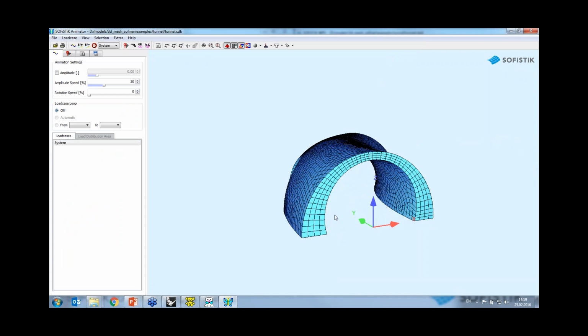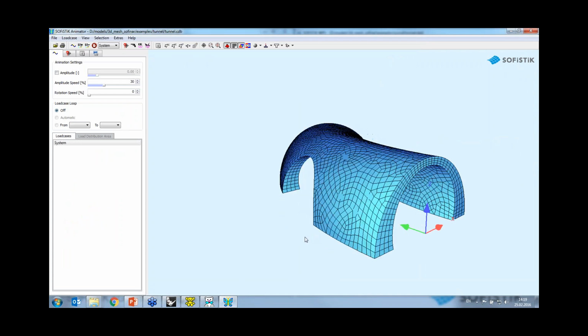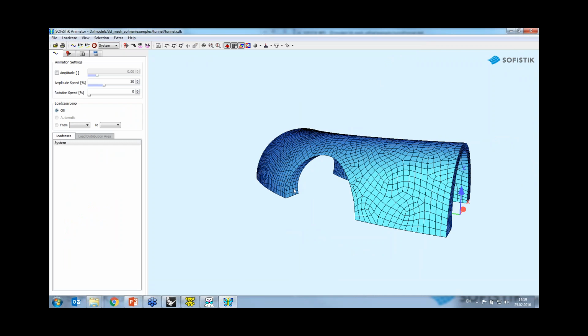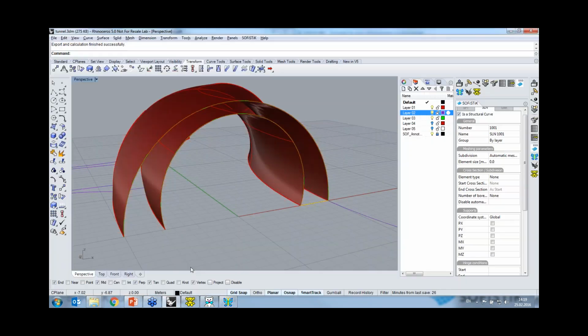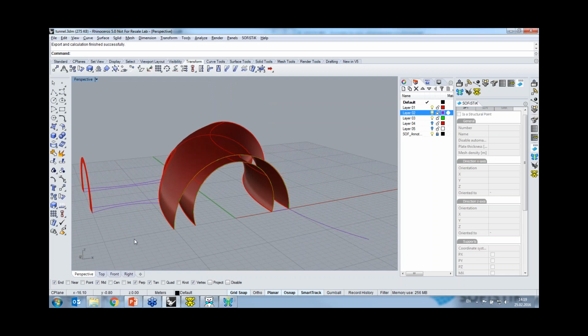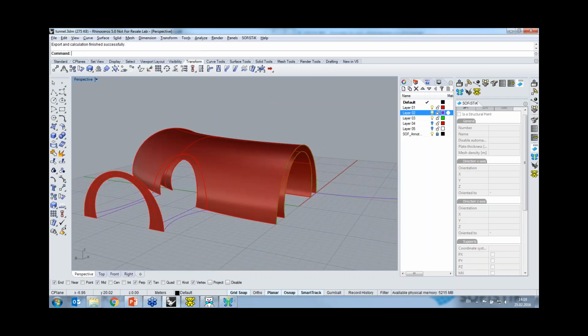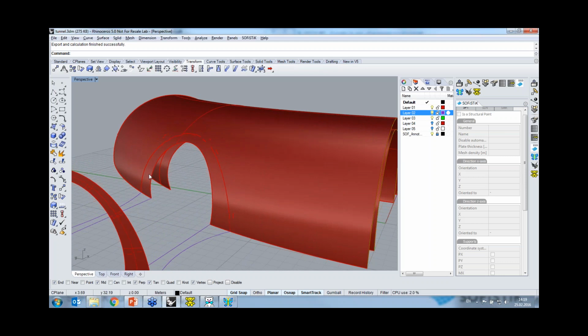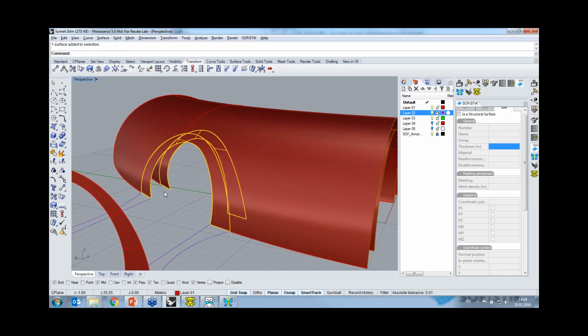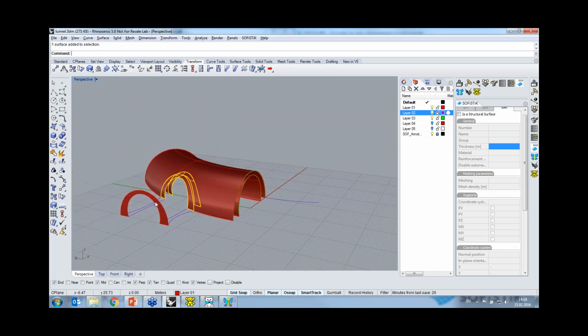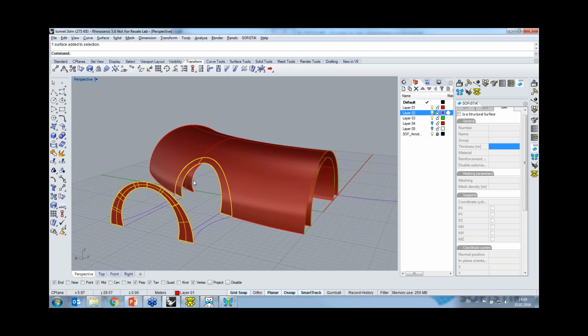So this is our model after the first lofting operation. We can see the brick elements that have been generated between the source and the target surface. Now let us do the same for the remaining model. This time we will do things a bit faster. Now we want to loft between these two areas, and we also want to loft between these two areas.